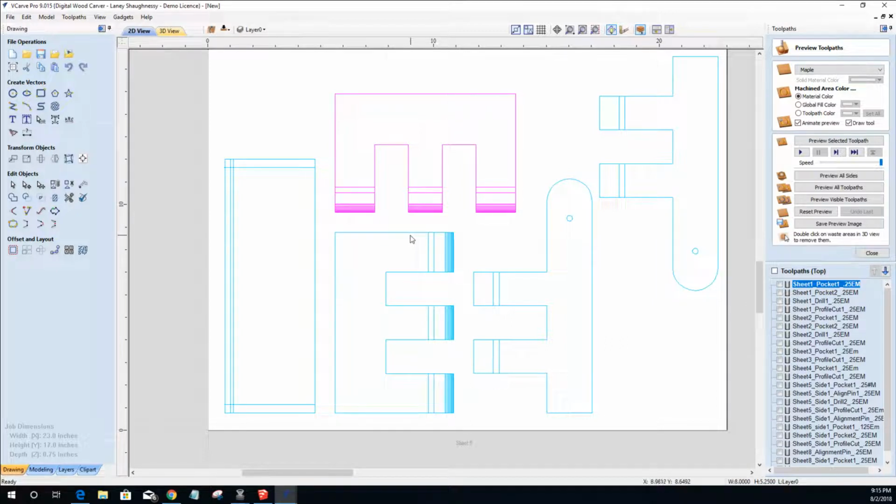Now I would typically either sand and round this over, or round it over on the router table, or use my bandsaw to cut the edges off after it's glued up. Or you could just round it over with a round over bit on the CNC. But I'd much rather, because these two parts get glued together to make one 1.5 inch wide part and everything.